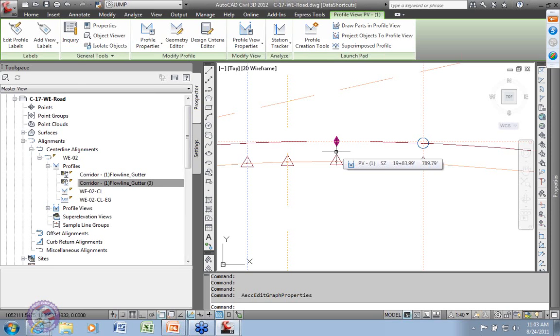Perhaps I wanted to produce that profile to then edit it and make a new design profile, because I do want to do something with the flow lines, because I do need to deal with the storm drain as it goes down the street. That would be faster than editing all the individual stations or doing ranges of edits in the section view editor, by simply doing a design profile. Here's what my corridor is going to put out now. So that makes a good start point.